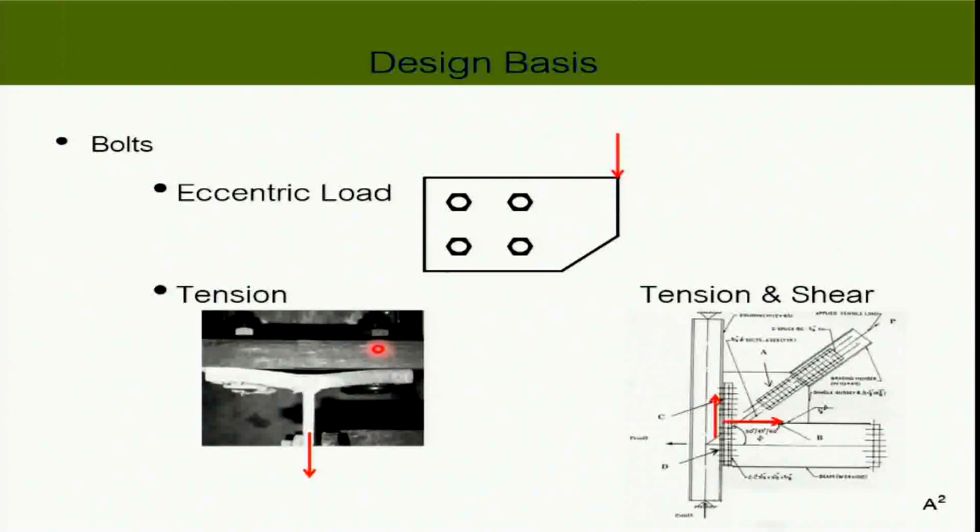And this is the bolt under tension, but this case I'd rather not talk about today because if your plate here is too thin, it can deform and help pry the bolts out of the support. We have what is called prying action. And now your bolt will have to carry both the tension itself and the prying force. So overall, we have less load carrying capacity for the bolts. Not good. We can solve this by making the plate thick enough.